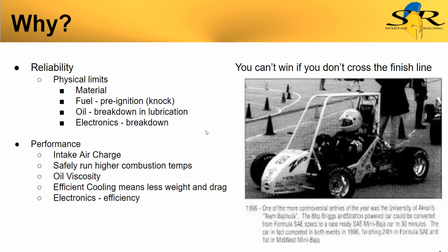And then it also affects performance. If we can cool down the intake air charge, we can get more air into the engine to burn more fuel, and we can safely run higher combustion temperatures. We can maintain our optimal oil viscosity to reduce friction and help with lubrication. And then if we do it right, efficient cooling means there's less weight and drag if we optimize our cooling system.